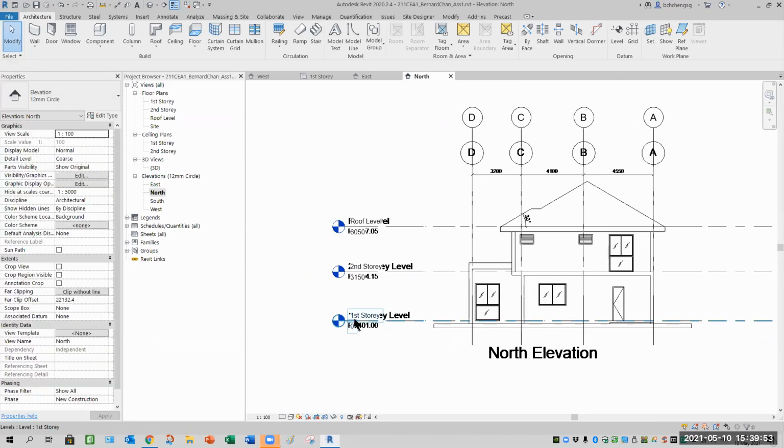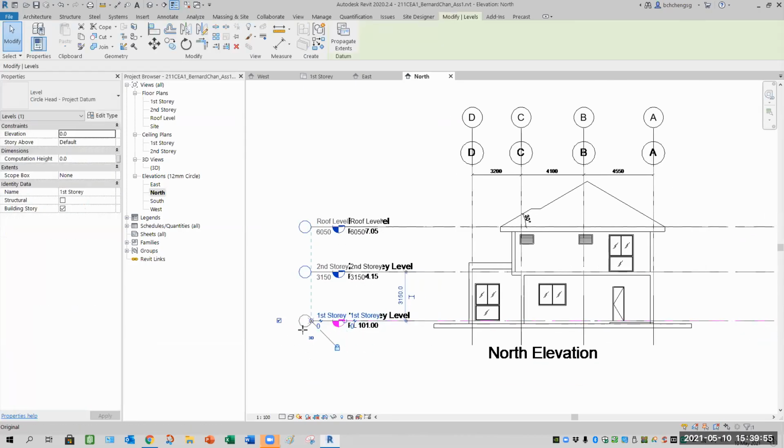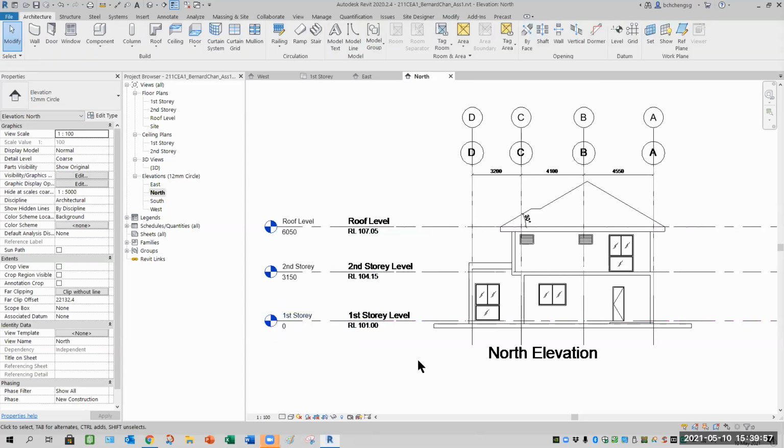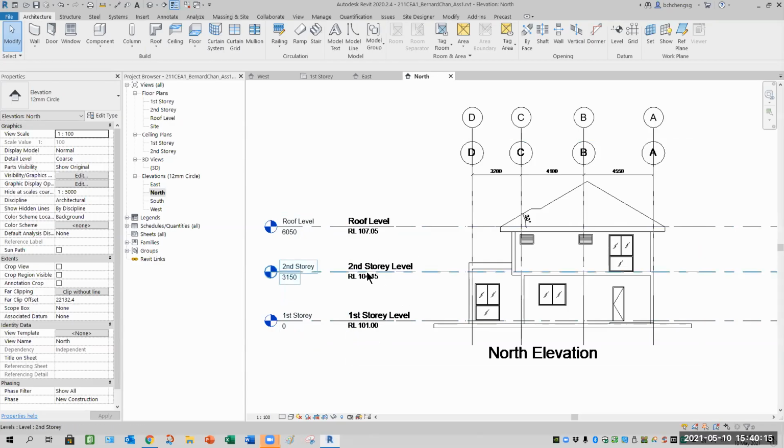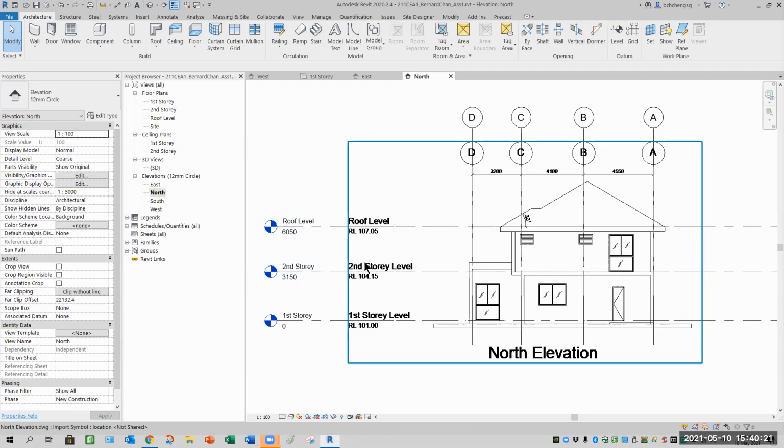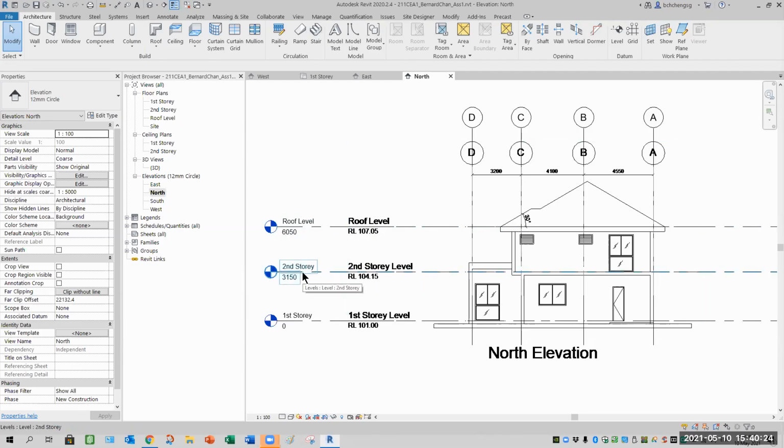So if I select my drawing, I could drag about like this. See now. Normally we link the CAD file. Purpose is to be able to extract the datum, which is the grid and your level. So once you already created them, you can hide. No need to show or repeat the display. These ones from CAD can be hidden already. This is ours, we need that.